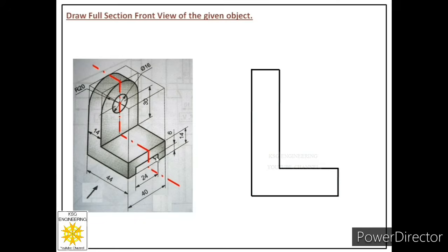Then in the next step we will construct this hidden face, and for that first of all we have to locate that face. And in this face 2 points are visible to us. So let us pick this point and let us locate this point in the front view or the previous face drawn by us. So this face in the object is over here. And if we move from this point towards this face, then we will reach this point, or we can say this point is behind this point of the first face, and that point is over here.